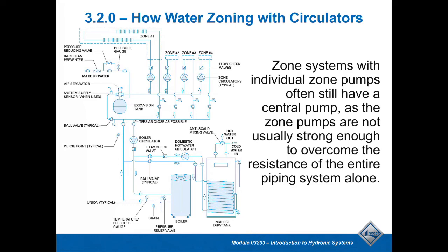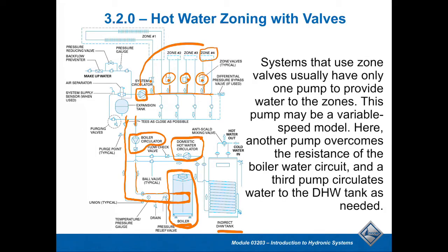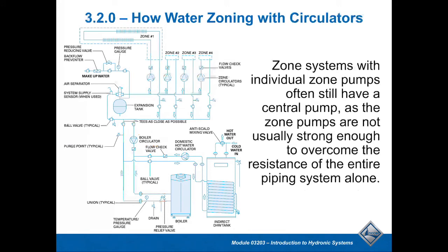So certainly as an alternative method to this, one of the things that I'm going to point out on here is the same scenario as the previous system that we just looked at, where they have a primary secondary system. They have this pump in what I'm going to call the primary loop, and it's going to deliver water to these zones respectively, whichever one is calling. And then they return back into this return loop. Absolutely every single one of these loops is going to need some sort of a balancing valve on the return side, and that's standard practice in the industry. Everybody would need to do that.